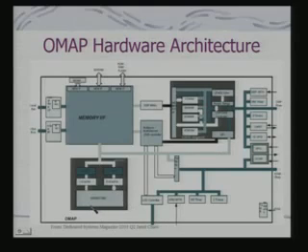In case of ARM core, in fact ARM9 is a Harvard architecture based processor, so you have got an instruction cache and data cache separately, and then it has got its own MMUs, memory management units. Through this, this processor is using the memory interface to access external memory.